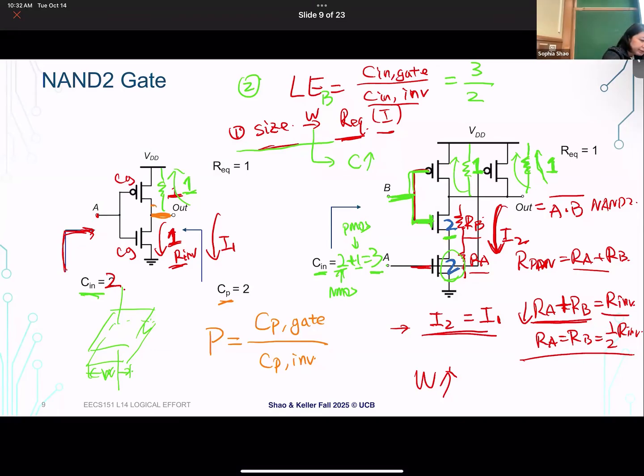So here, again, we have the drain capacitance for both PMOS and NMOS. Those are the two things we're driving. And when it's sized at 1, the parasitic capacitance from the PMOS side and NMOS side is basically 2 here. One from the PMOS, one from the NMOS. That's the parasitic side. And you can do the same thing again from the output. Whenever we talk about parasitic, we look at what capacitance we see from the output. That's the parasitic capacitance that we're driving, right?